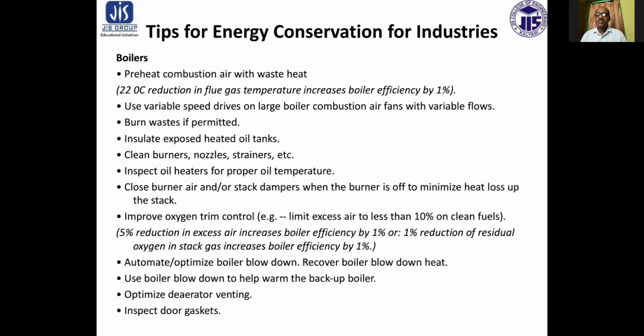So fuel in the combustion chamber will similarly vary. So variable speed drives, that is, combustion air fans with variable flow, are required to save the energy.